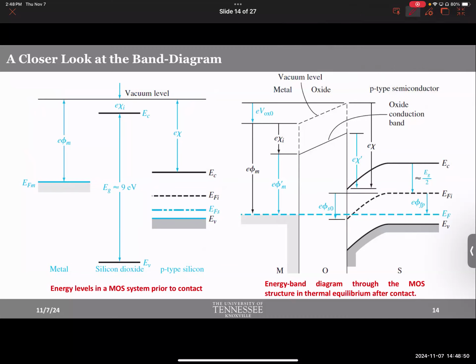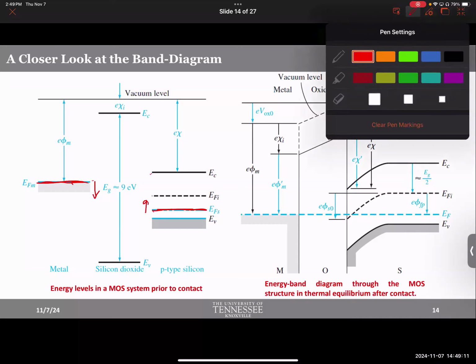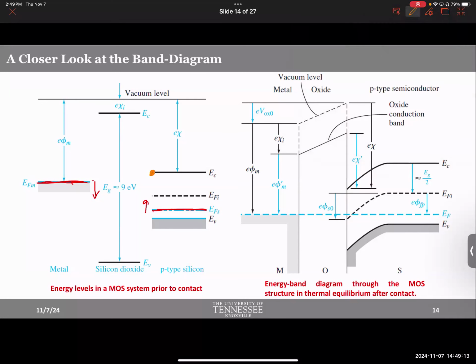We did that many times. I'll do it one more time. It's so important, and I'll use the trick that Professor Jackson taught me again. When these Fermi levels try to come towards each other, this one will go down and this one will go up. Don't you think? They will all contribute. And I told you that these other bands in the semiconductor are like sticky. They're basically stuck here at the edges. But the rest will follow the Fermi level, right?